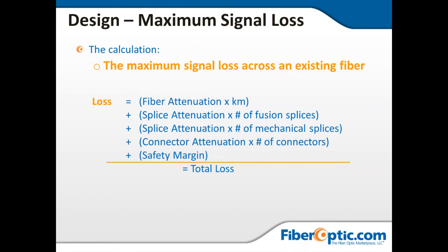Now the connector pairs are something else. The EIA/TIA mated connector pairs would be a maximum of 0.75 dB. Now you could say, well, that's the standards. Are standards really good? And you might say, no, what would I really expect on a high-performance system today? And so 0.75 is usable as a budget to run your calculations.